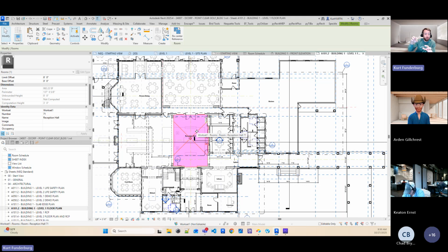That allows us, when we put something in the space in the floor plan on the PDF, to create the spreadsheet for us, showing that in all these spaces you have these items to look at. It saves a whole bunch of time when you're doing a huge punch list. I'm in the reception hall; in the reception hall, I need you to look at the flooring, and retouch the paint in these areas. When you start dropping items in from your tool chest, like touch up paint, check base finish, the things that we go through with the punch list, those can be easily put into a space in Bluebeam because of the rooms that are set up in Revit.